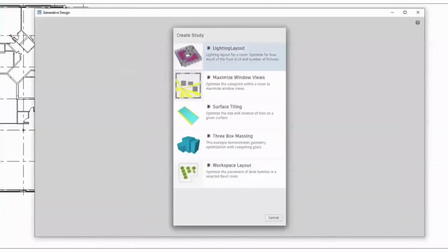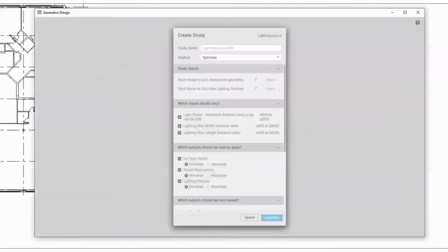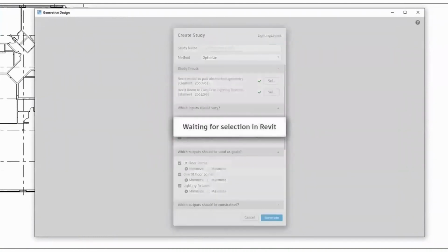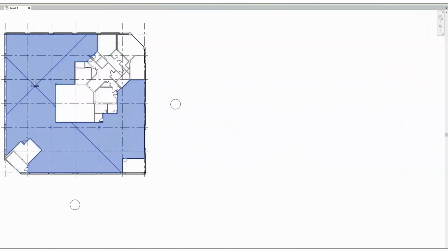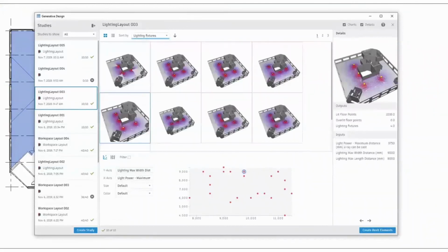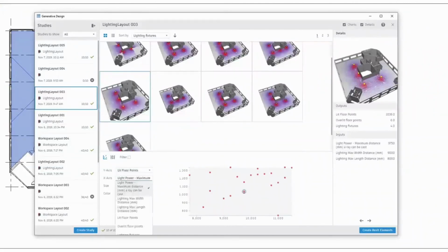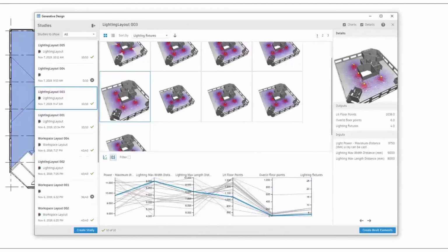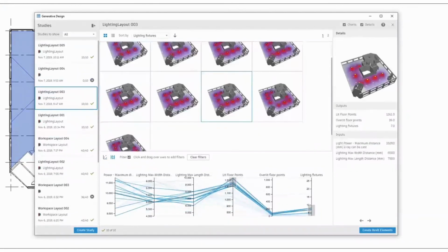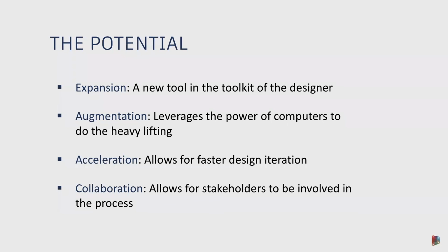And this is talking about a lighting layer. So we're trying to find the optimal spread of lights. So we want to have a lower cost, we want to have a certain level of light saturation across the entire set, and we don't want to have too much overlap in this as well. So we go through, we select something in Revit, it's interactable, it understands based on the room context, the fidelity of that room, it can pull in data associated with that room, and it's going to go and place a whole bunch of different lights, and then optimize those relationships based on your goal constraints. So it's going to design a whole series of random ones at the outset, and then it's going to take those through and towards optimality again and again through an evolutionary process.